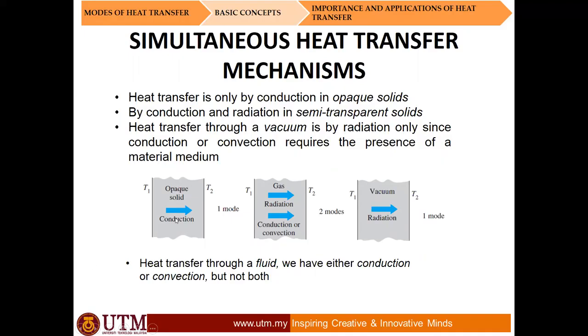So if we are dealing with an opaque solid, the heat transfer internally is through conduction only, one mode. For gas, it can be radiation, it can be conduction or convection, a combination of radiation and conduction, or a combination of radiation with convection. In vacuum, only radiation. So that's what is meant by simultaneous, where you have two mechanisms occurring at the same time. For heat transfer through a fluid, we can have either conduction or convection, but not both. If you have motion of fluid, the heat transfer is going to be convection. If no motion of fluid, the heat transfer is going to be conduction.